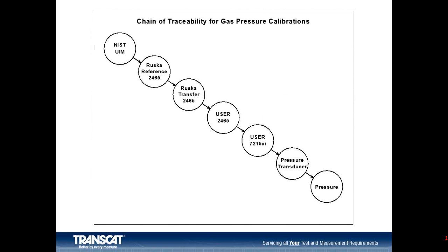In some years past, the definition of traceability was limited to this concept that a measurement at the end of the chain was traceable if you could demonstrate an unbroken chain of comparisons to the top level. In this diagram, the upper left-hand side that's labeled NIST. In fact, the description at that time was typically traceability to NIST.